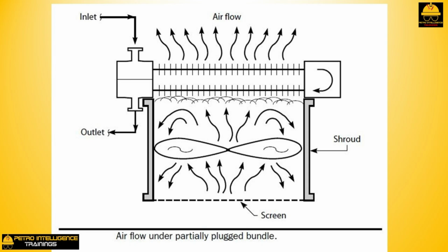The only way to seal off this gap is to use strips of plastic or Teflon attached to the inner wall of the shroud. When the fan is turned on, it will cut through parts of the plastic strips and create its own seal. Field results have been positive, and the strips, called tip seals, can be purchased as a retrofit kit from air cooler vendors.